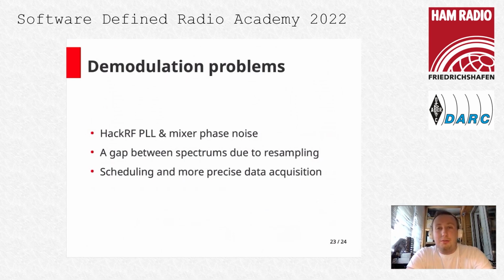What about signal demodulation? Is it possible to demodulate the wideband receiving signal? Unfortunately, not at this point, because even when we synchronize all these boards with the same clock signal, with 1 ppm synchronization, it didn't help us solve the phase noise problem of the HackRF PLL chip and HackRF mixers.